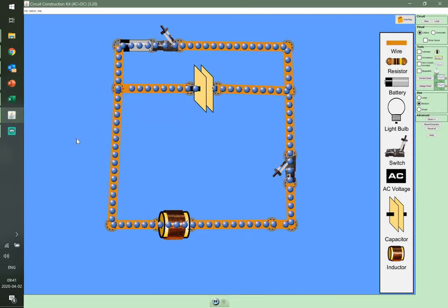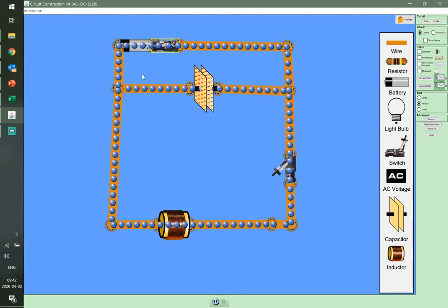So here I have a simulation of an LC circuit. I'm just going to really quickly, with this disconnected up here, charge up the capacitor so that we have some energy in here. Because if we just connect these two things together with nothing, then nothing's going to happen. So we have to charge up the capacitor first. Boom. There's a little fire because there's no resistance in between. So I'm going to pause it and we're going to connect this.